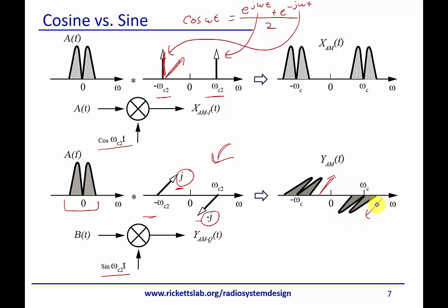And so you can see we have this has a complex magnitude, this has a real magnitude. Just to be clear, they both are real signals because they have negative and positive frequencies that match. It's just that if we set cosine to be real, then sine is orthogonal to it, and that's where we get this J. And there's a little bit of trickery we can do with this.